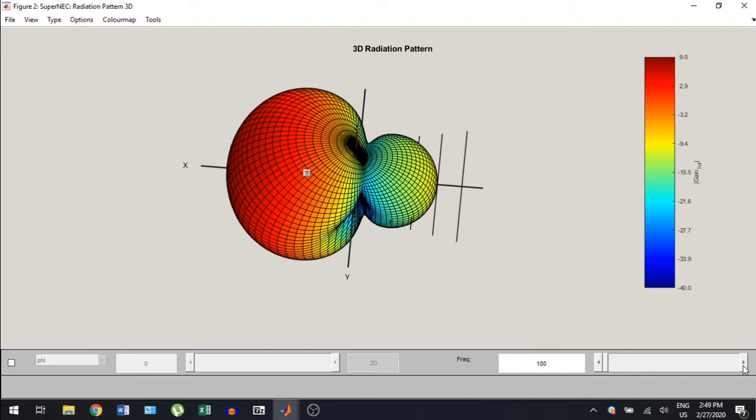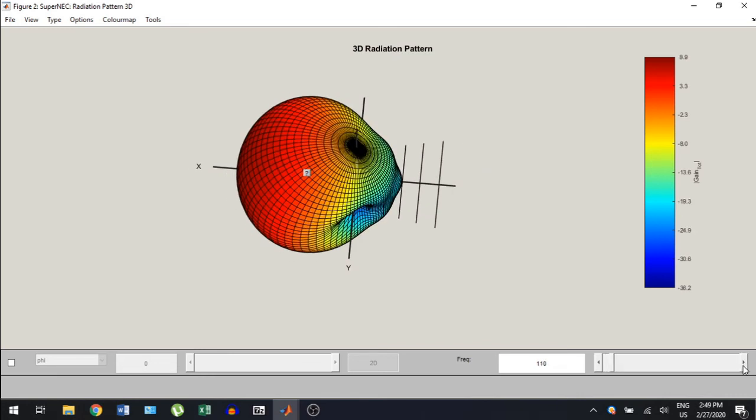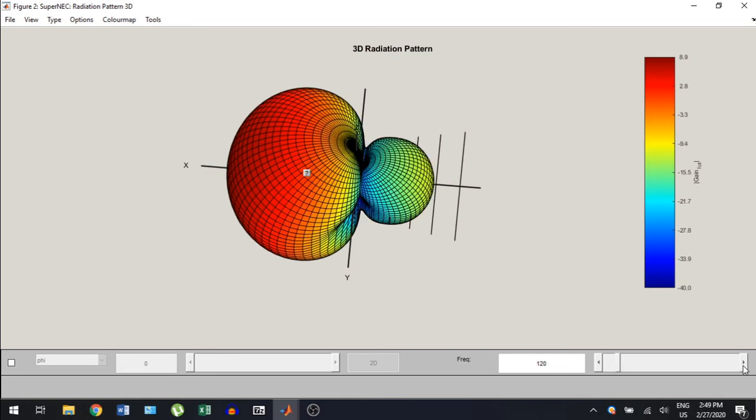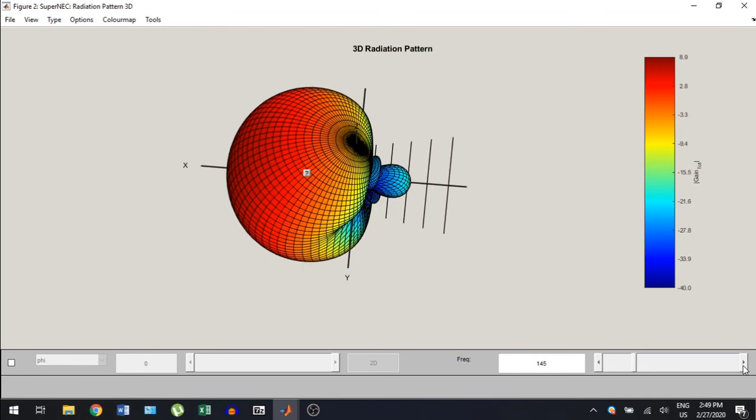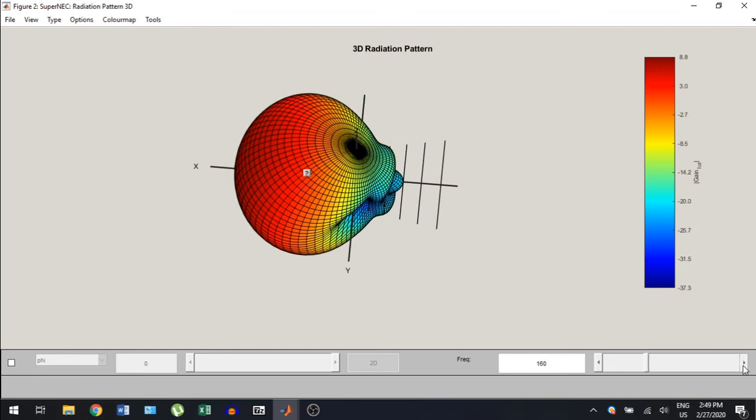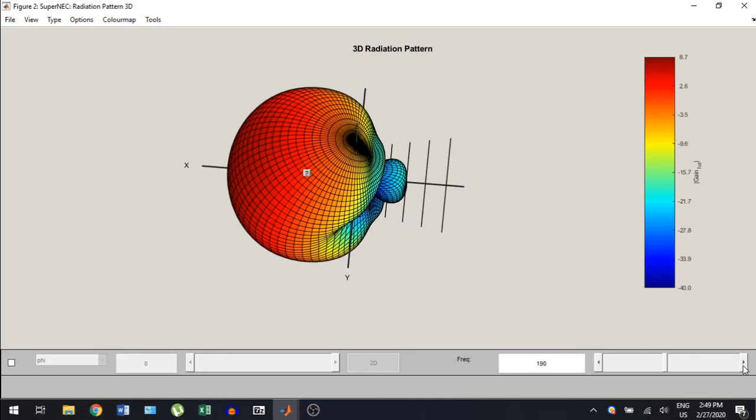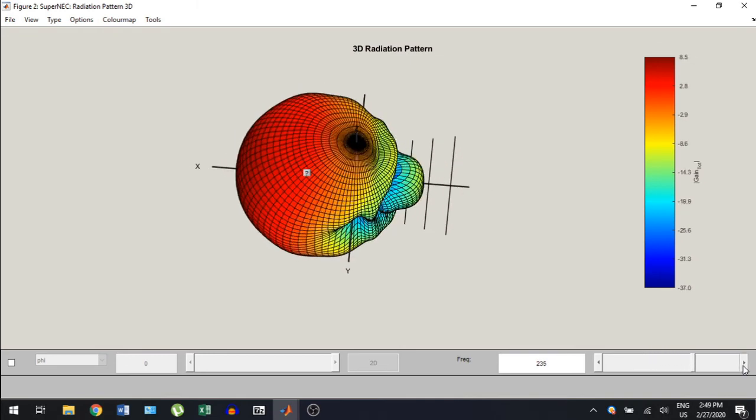We once again have a very convenient frequency slider available to us. The frequency slider, however, will always jump to the nearest available point of data, and it's often based on what sort of increment you set up in your simulation settings. We did 5 MHz, so there we go. You can see it sort of balloon out and change as it moves through the structure at different frequencies.